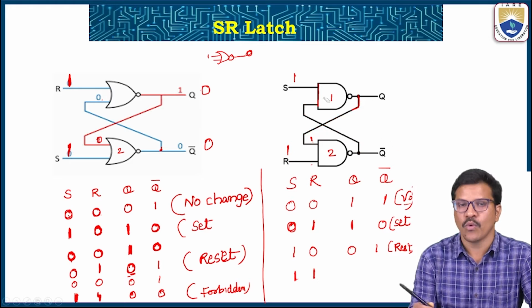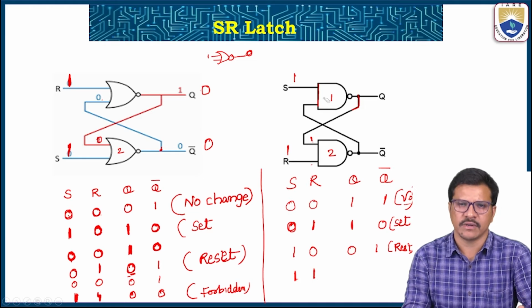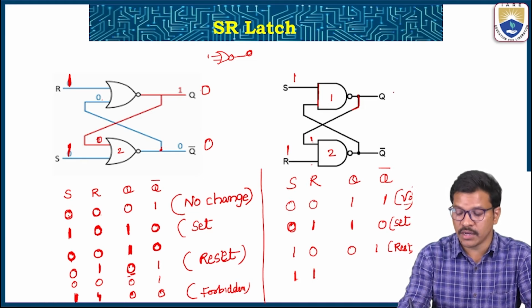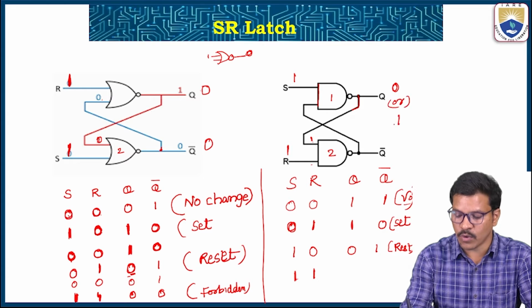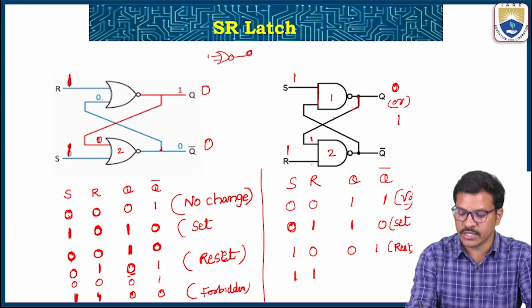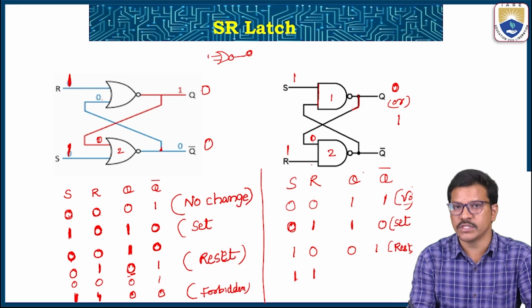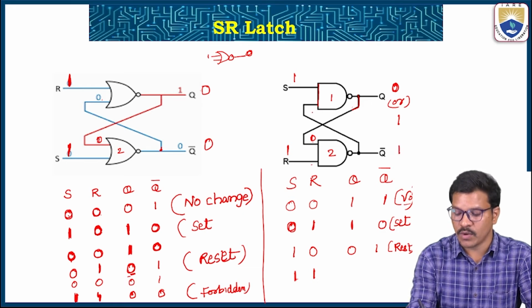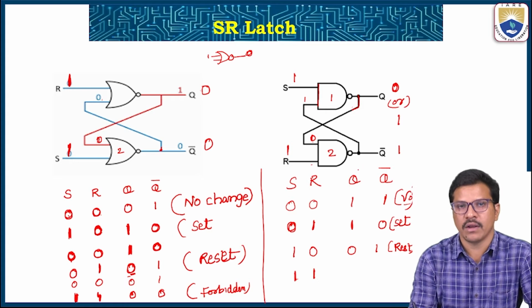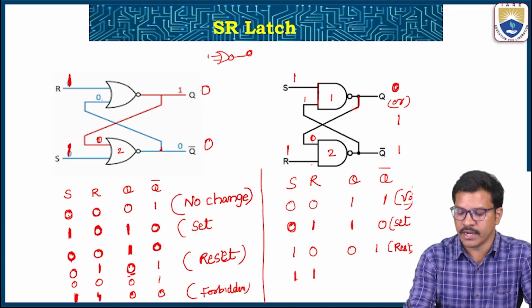So now by applying an assumption, by assuming that it is logic 0 or logic 1. If it is logic 0, that 0 is available here, and 1 and 0 in the NAND gate will give a 1. That 1 is available, and 1 and 1 for the NAND gate automatically give 0. So previously we assumed 0, and now we get the 0 output.